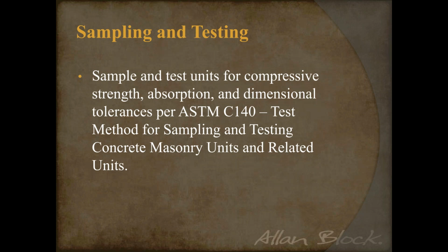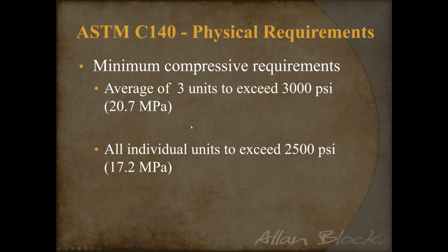So what we're looking at here for compression is pretty straightforward. We're going to take 5 units, and 3 of them have to exceed 3,000 psi or 20.7 MPa, but all of them have to exceed 2,500 psi and 17.2 MPa.